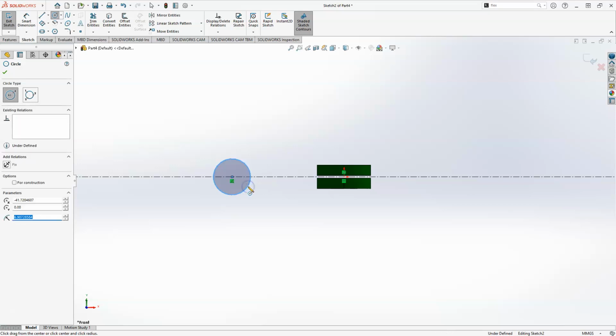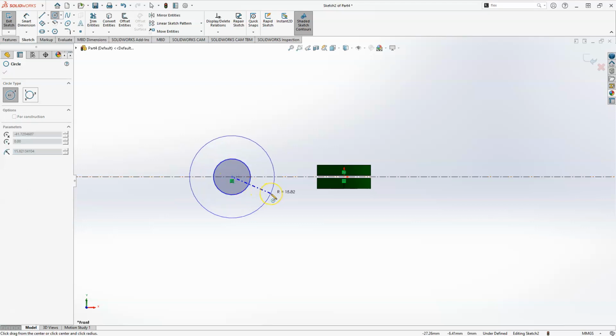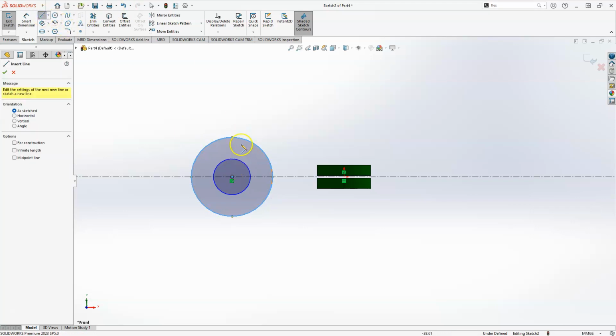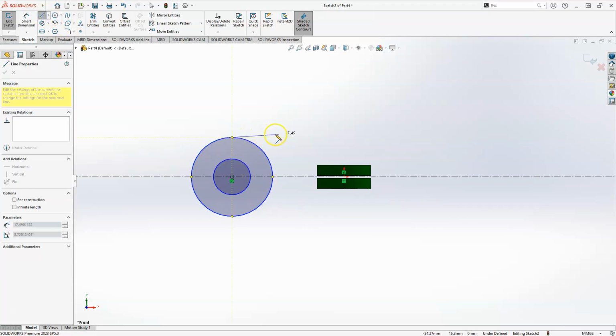I would like to use a different technique from the one that we used to draw the previous profile. So I would select another circle here, and then go to the line, and pick a line from this point, horizontal tangent all the way here, come here, it should be this point, and then SolidWorks gives us the line, and then pick this one.